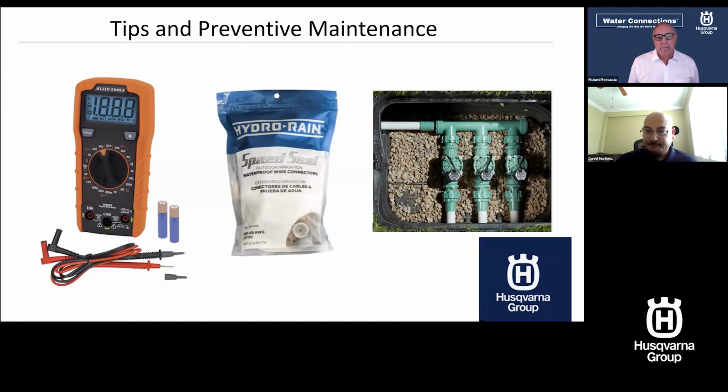Save yourself some time. And then Hydro Rain, we make a very high quality wire connector. If you recall these little ones I showed you indoors, try to stay away from those in a box, especially if below ground. They're not rated for below ground use. Use something with a nice waterproof connector.